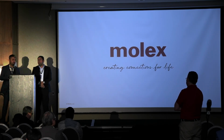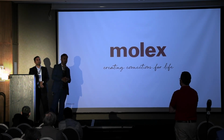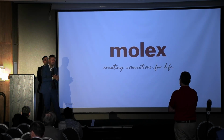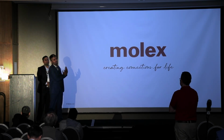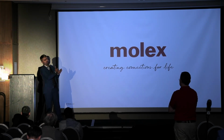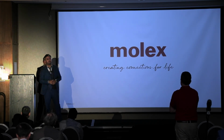Yeah, so Gustavo, to your point, until the condition for an accidental antenna is there, it won't be a problem, because the problem is happening because of pin 4 not being taken care of on the cable side. So if you are using shielded twisted pair or unshielded twisted pair, the problem is from pin 4 not being connected, so that a complete standing wave pattern is generated on that. Because the signal is going back, until that condition is there, it doesn't matter whatever cable we use, there will be a problem. This is what our studies have shown us.